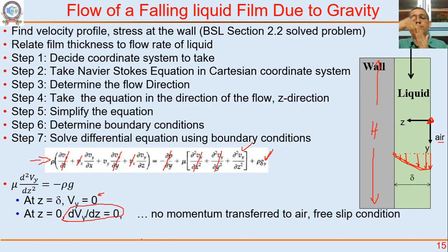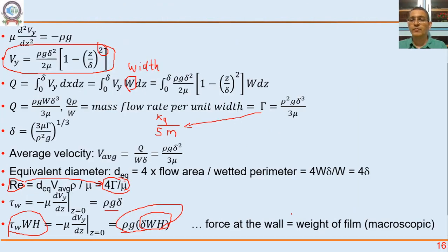Steady state in the sense Vy is not changing with Y. There's no acceleration. Why is there no acceleration? Gravitational force acting on the liquid is exactly balanced by the frictional force, stress at the wall. Okay.